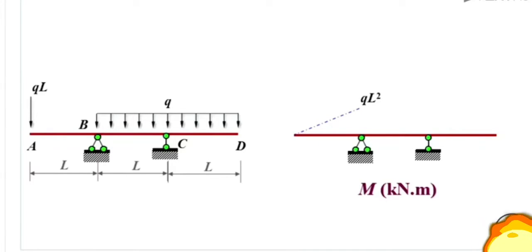These sections B and C are control sections. If we determine the section C's M, we find that actually the BCD part is a straight line. Then we take this dashed line as baseline. For the AB part, no other external loads are acting on it, so we just use such a straight line to substitute the dashed line. For the CD part, we could take this dashed line as a baseline and superimpose a parabola, because this part is under the action of uniformly distributed load.